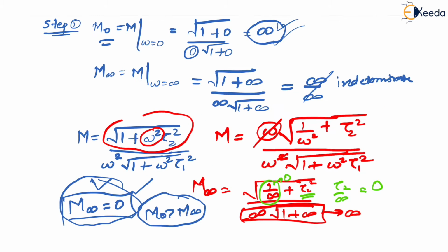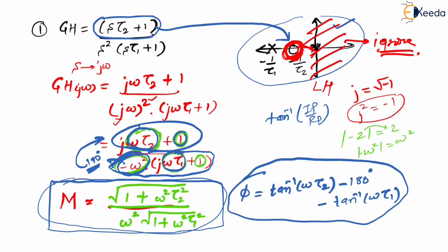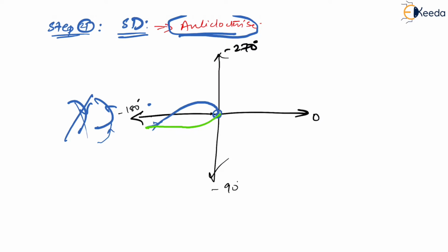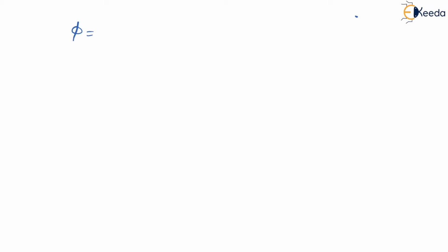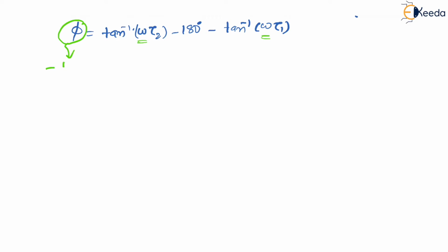What is that angle criteria? Our equation of this phi. Let us use that and try to find. Yes. So our phi is nothing but, right? Yes, definitely. Now I need to find the value of frequency for which the angle is minus 180 degrees. So let me put phi as minus 180 degrees, which is equal to, yes, now tan inverse.